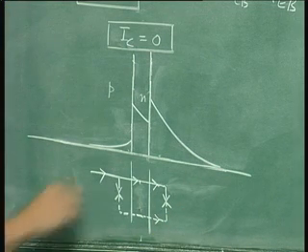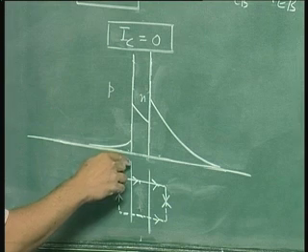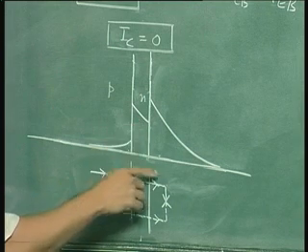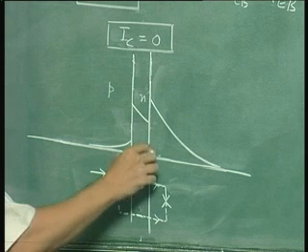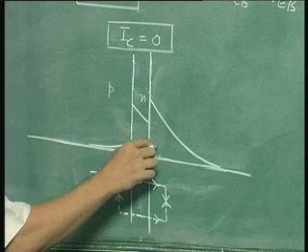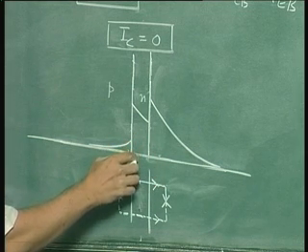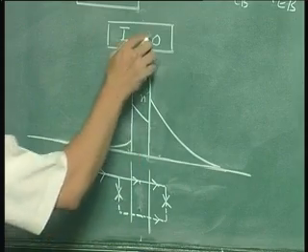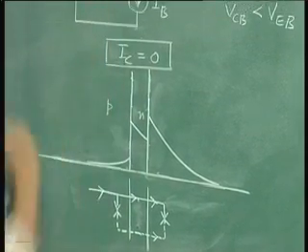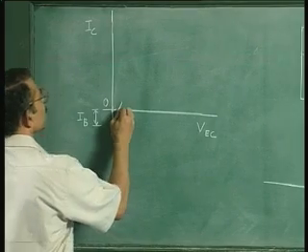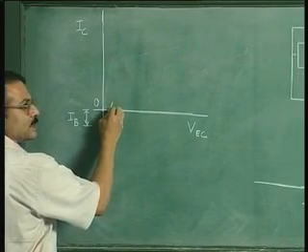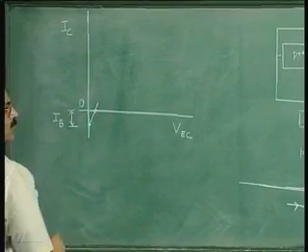So in fact one can analyze this situation, write down equations and impose this condition that this whole hole current should be equal to this electron current, and one can determine the value of the collector base voltage and the emitter base voltage, and therefore the value of VEC for which this condition would occur. So that completes the discussion about this condition, that is IC equal to 0.